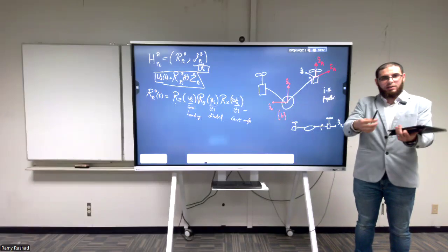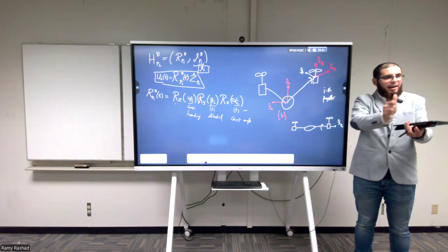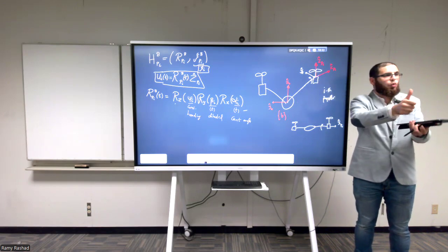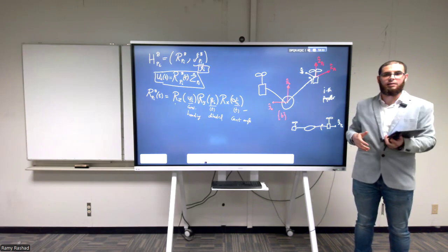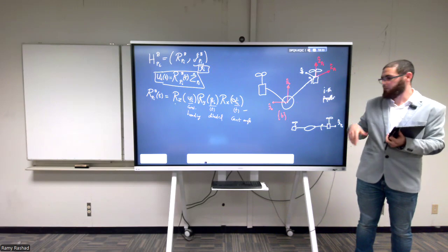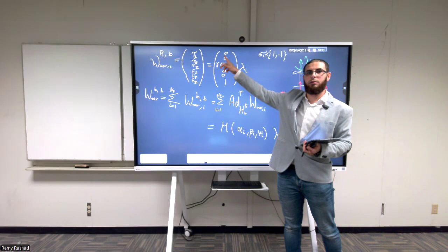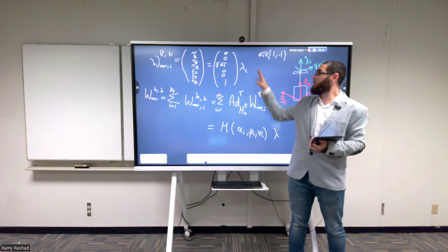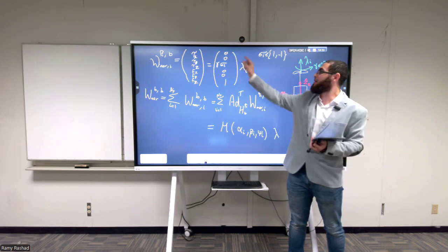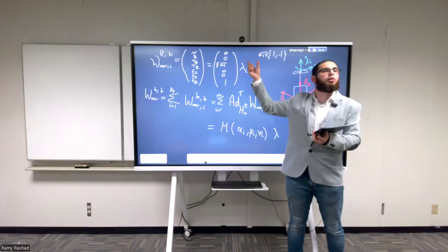Sometimes when you're designing the propeller itself, there are some inherent angles that are already there, like 1 degree or 2 degrees or 3 degrees that are just inevitable when you're designing the structure itself. Which means that if you have here some components that are not zero, again, they will get multiplied into this huge matrix. And this is a nice way that you can play around with these small numbers and see how sensitive your drone design is to these small errors, right?